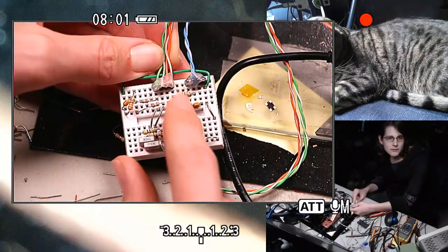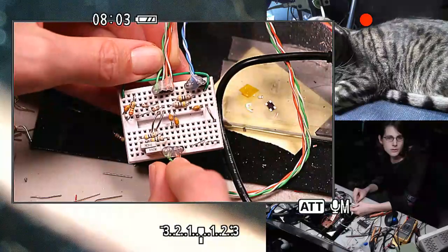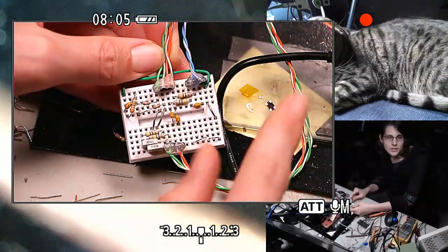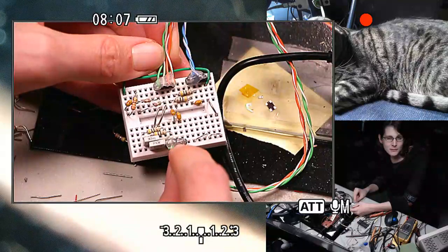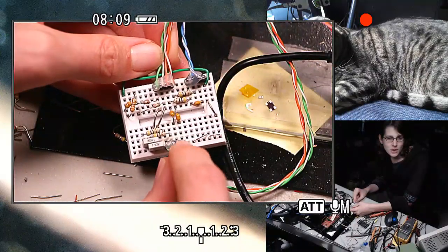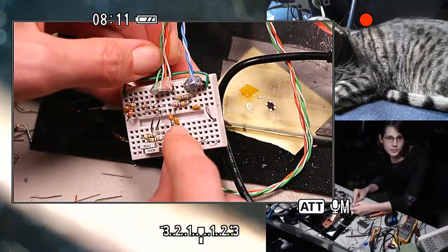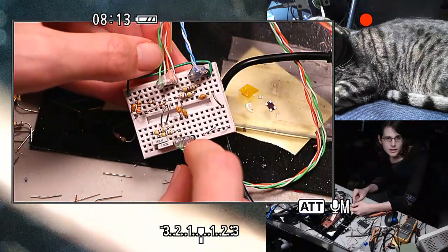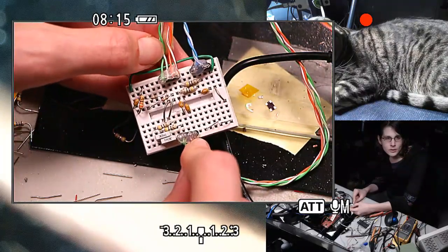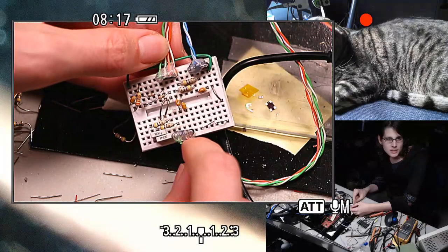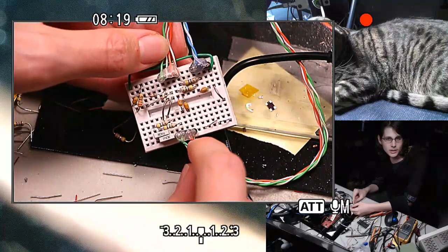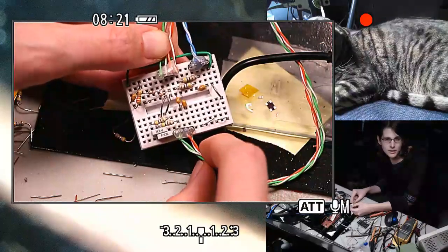But then I'm capacitively coupling those signals over to the inputs on the TI board, which already seem to have enough biasing resistance. So when I look at this signal, it looks pretty good. It took a little bit of adjusting capacitances and stuff, but I got it looking pretty good, and the TI chip receives it just fine.